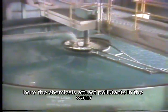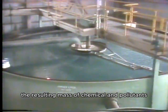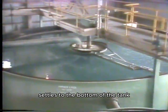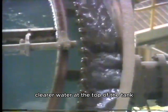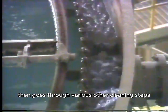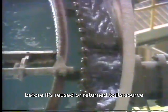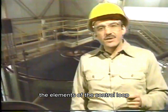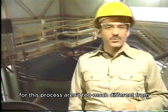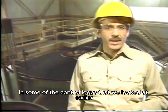Here the chemicals attract pollutants in the water. The resulting mass of chemical and pollutants settles to the bottom of the tank. Clearer water at the top of the tank is drained off into another tank. The water then goes through various other cleaning steps before it's reused or returned to its source. The elements of the control loop for this process aren't too much different from the control elements in some of the control loops that we looked at earlier.